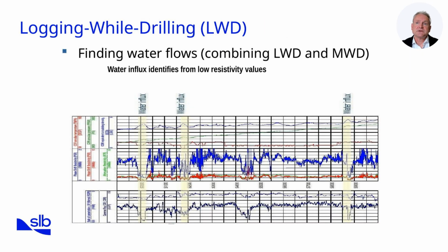This slide demonstrates how logging while drilling data can be used in combination with measurement while drilling measurements to detect water influx in the wellbore. What you see on the log are multiple tracks that record different properties of the formation in real time as drilling progresses. The focus here is on resistivity, which is one of the most reliable indicators of fluid type in the pore space. Resistivity measures how strongly the formation resists the flow of electrical current.